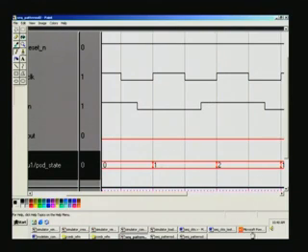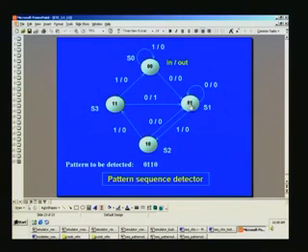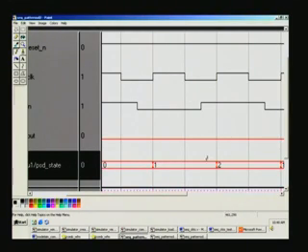See, in S1 state what we have here, if it is 1, it should go to S2, right. Otherwise it should remain right there in S1 state. Let us see what is that. If it is 1, it should go to the S2 state. So that means only at this positive edge this is being sensed, right, and this is the result of the previous one. So whenever there is a positive edge or the clock encountered, only at that point of time it is going to check the input here, right.